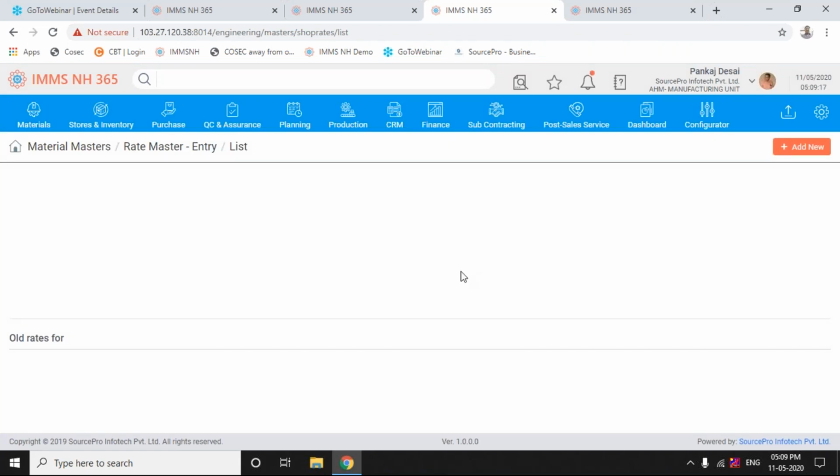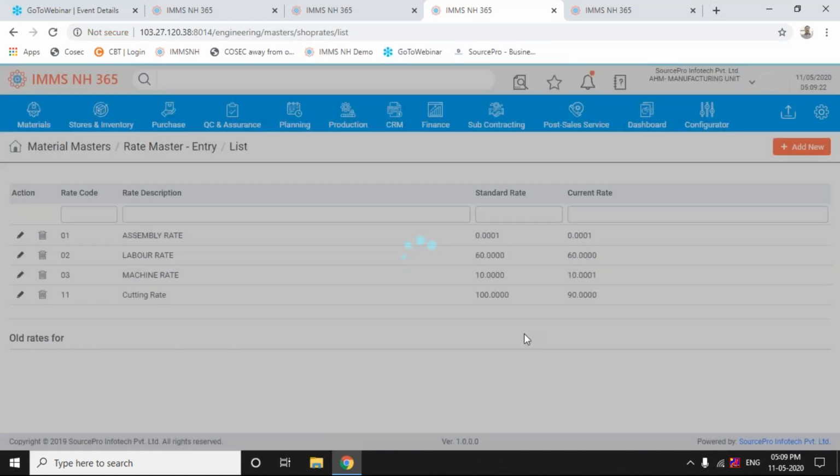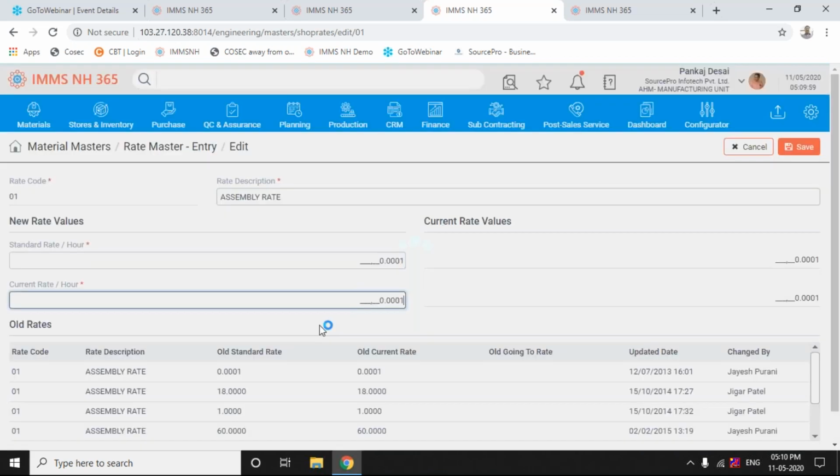So when there is a machine rate, normally a man is needed with the machine, so say when this CNC machine is run, it will cost 300 rupees per hour. So the facility to enter my per hour rate is here. If there is only labor, there is a facility to enter labor. So it consists of 4 different things. You need to give at least one. You have to say either it has machine rate or it has labor rate, or we have overhead 1 and overhead 2, which can be fixed overheads or variable overheads. Now, this is something that it is possible to define in the system.